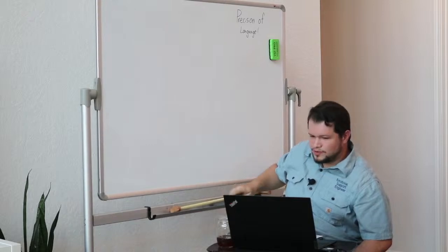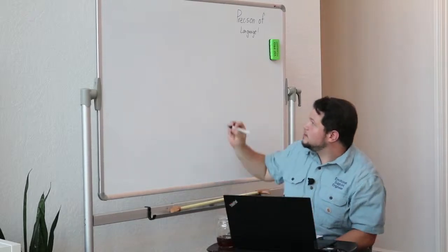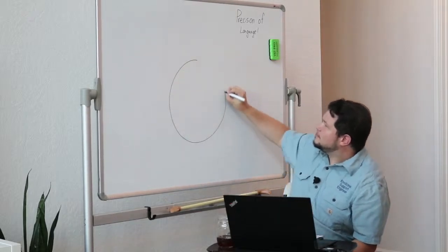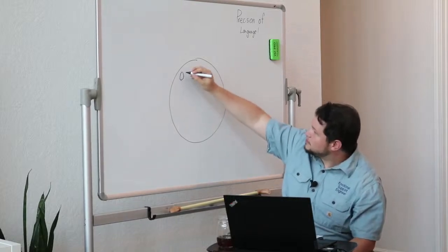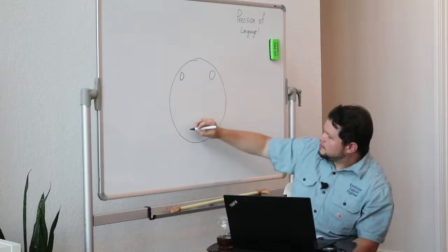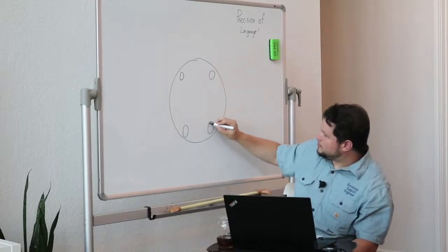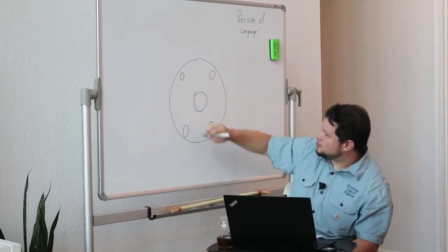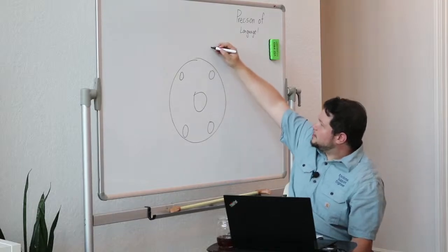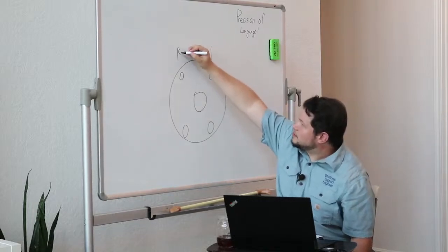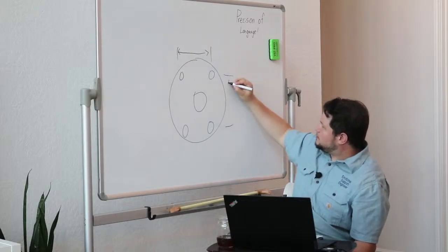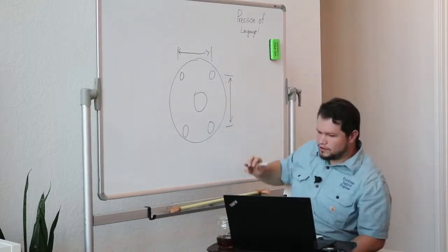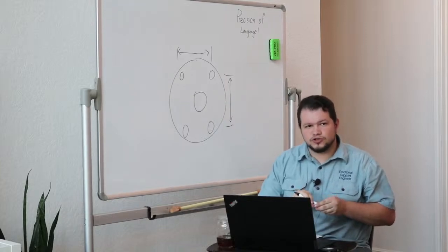Typically, there are two ways that motors are going to give you a dimension. Most motors, you're either going to be square or round, but they will have bolt holes. In this case, the motors have a bolt pattern like this, and this is your shaft coming out the middle. They will either give you the dimension here to here, which typically is going to be the same as here to here, or they will give you what's called the bolt circle.